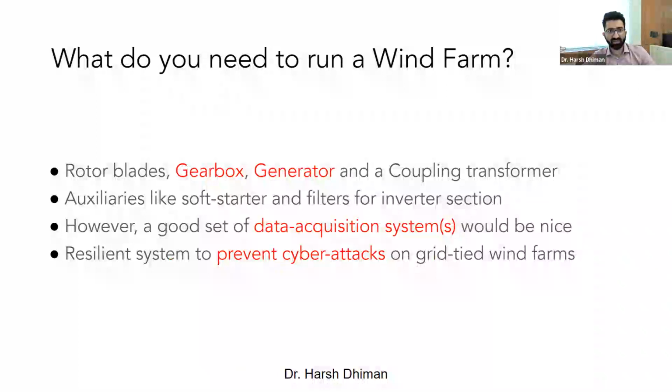The assessment is typically done on a wind farm area where you would be analyzing the average wind speed and the wind direction. And you do not do this for 1 or 2 days. This is something you do for years. Typically 5 to 7.5 years is the time spent on the resource analysis. Only then can you take a decision.